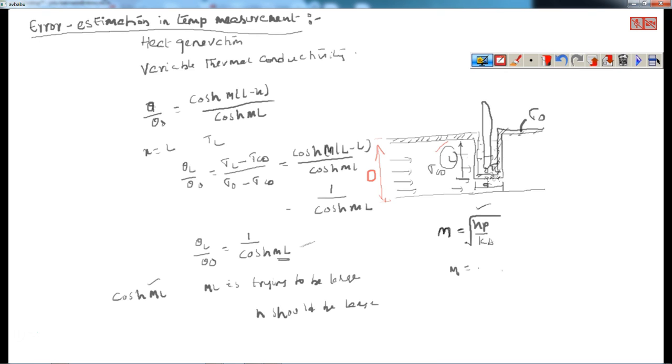So in that case, you need to make the tube, into which you are inserting your thermometer, obliquely constructed, and it is to be welded like this, and then you can put your thermometer like this. This is going to be the length, whatever length you want to put, L. Like that you can do the corrections, and then you can achieve the error estimations in temperature measurements.